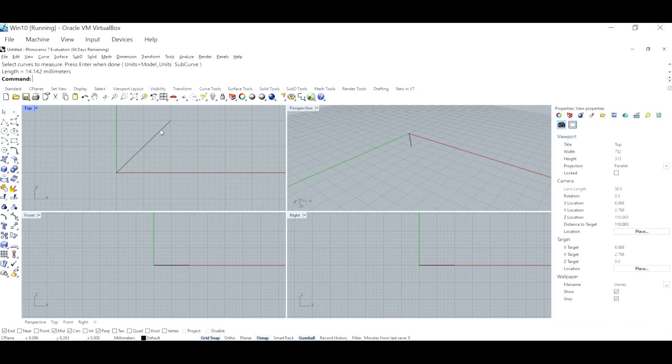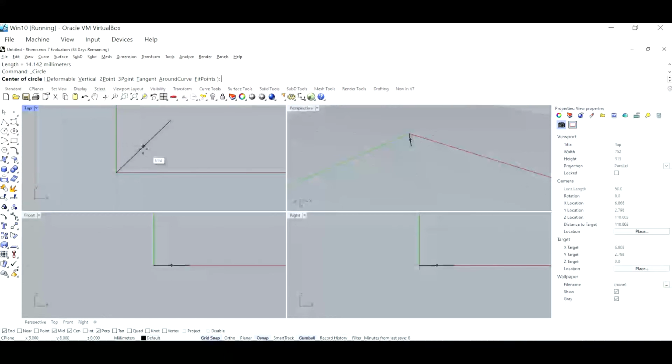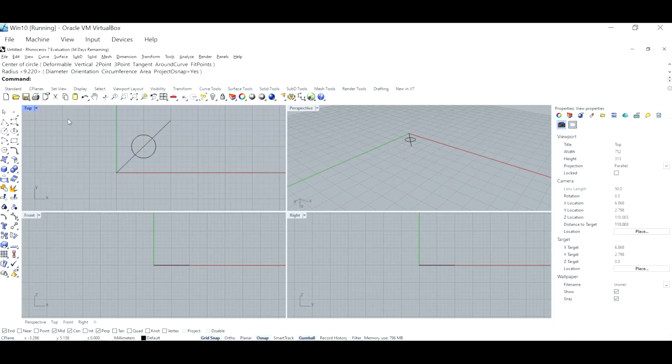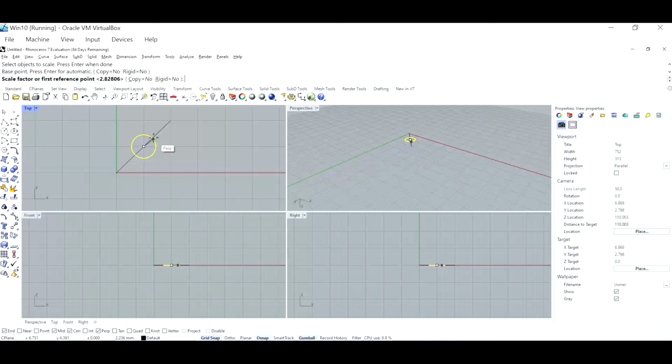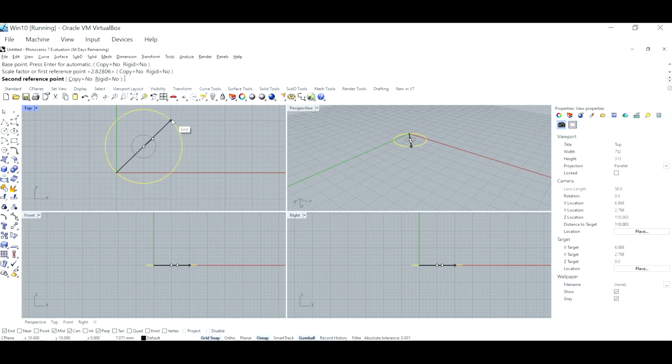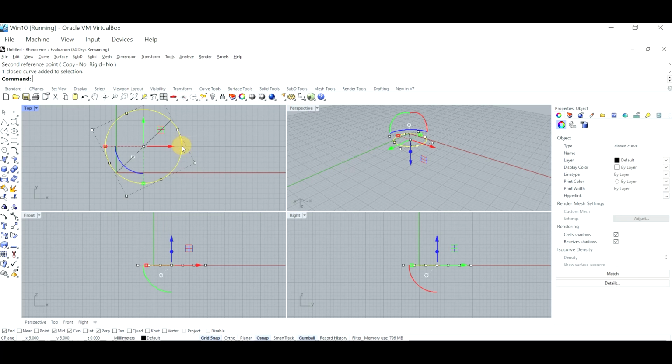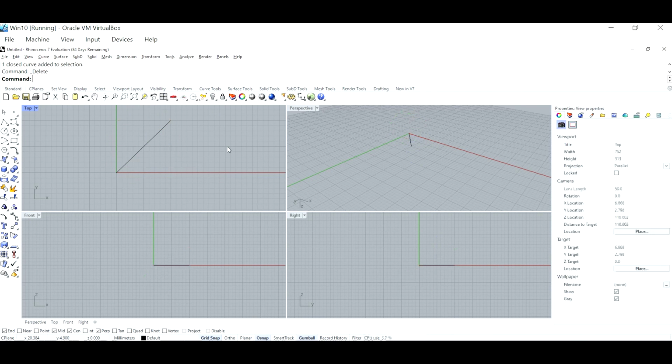You can place a line and then scale. So for instance, if you have a circle right at the middle, and then you do scale, which we'll go over with transformations later. This part, enter, and from this is the center, this is the edge, and then you move it here. Now your part is scaled to that dimension. And length is very useful, area is very useful, and the volume is very useful because when you want to 3D print a part, the volume operation will give you information about how much material or resin you'll have to use for your printing job.